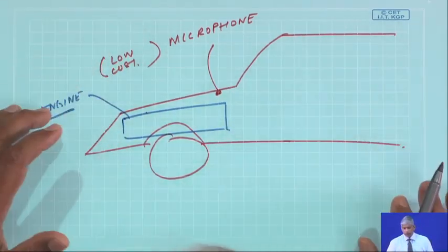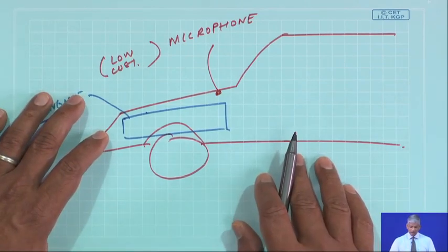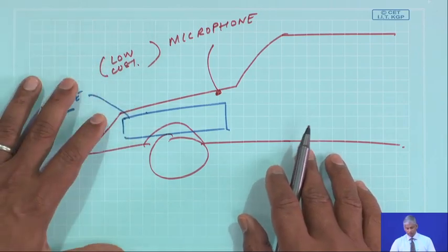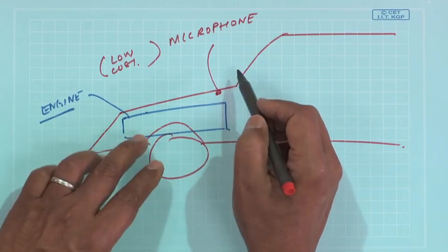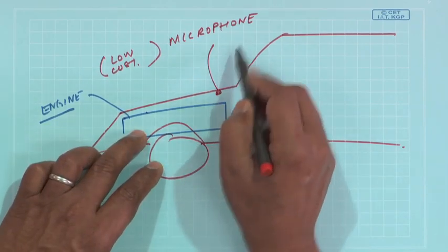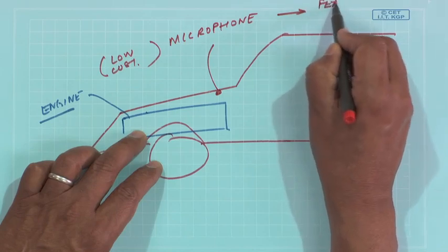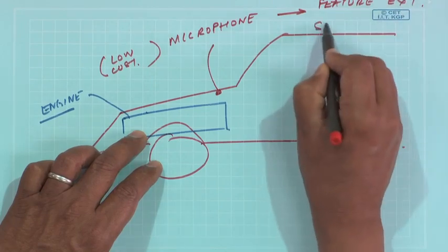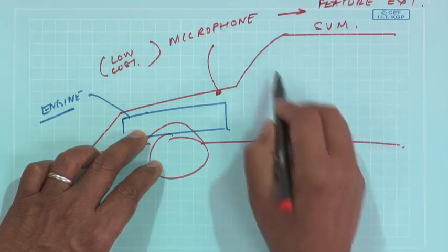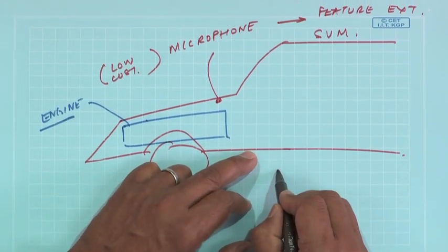I am giving you this idea, I have not patented it, because there is nothing novel in patenting it, but somebody could implement this in industry: put a microphone, have the features extracted and use an SVM fault classifier to intimate to the driver that there is an engine fault.